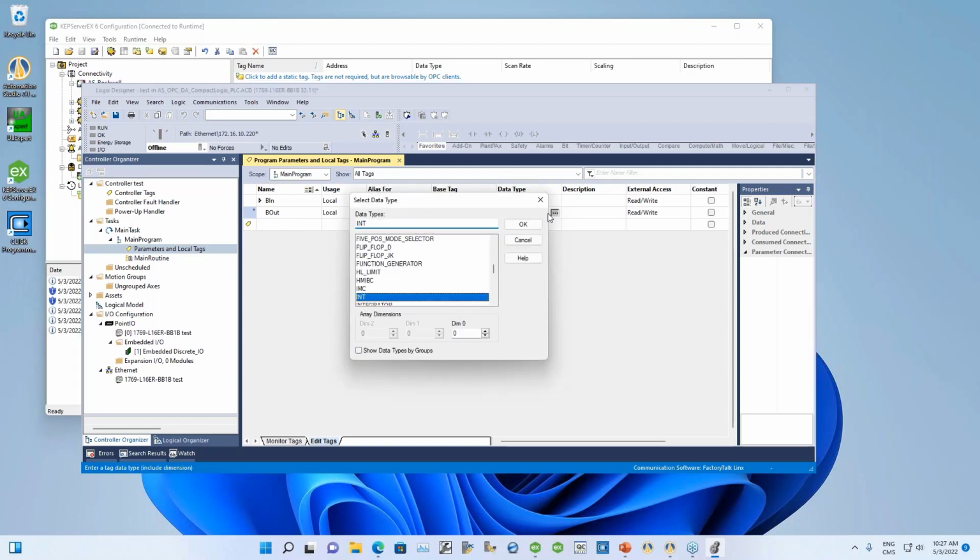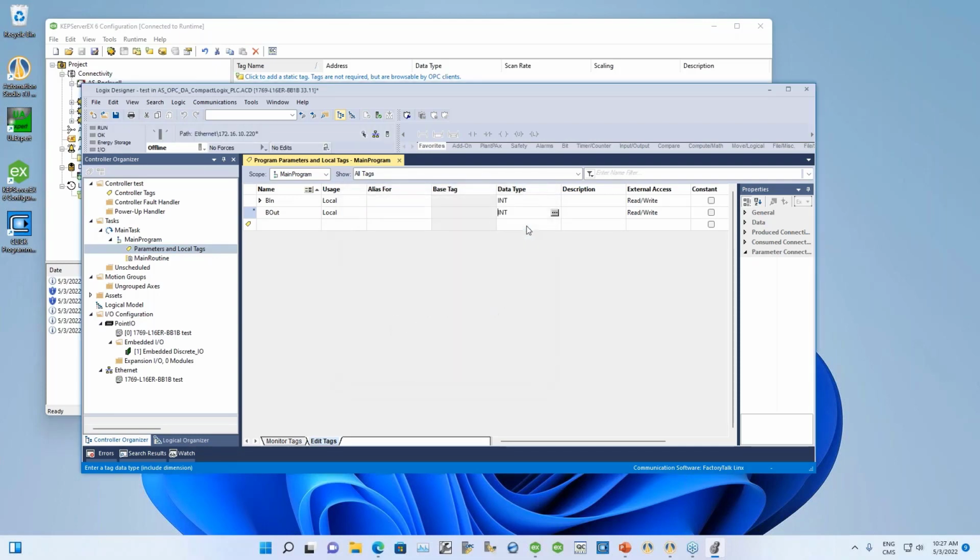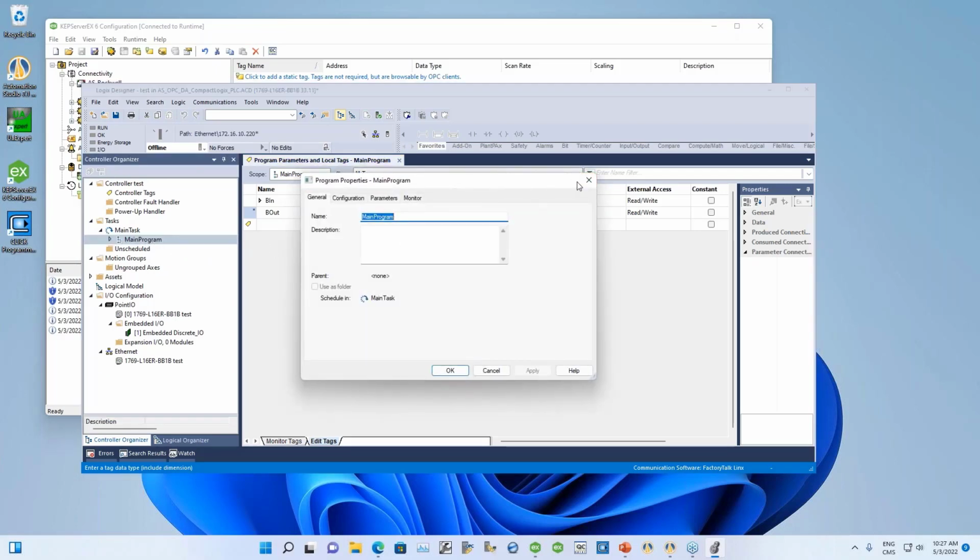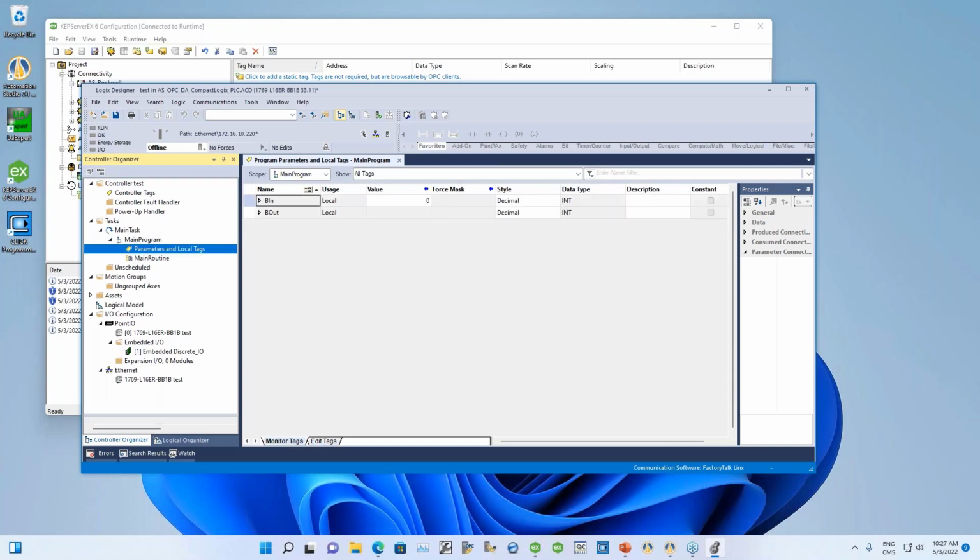And then it's int. For you guys who were doing PLC programming, you're going to come and ask, why are we doing that? We should be using registers, for example the ones in the PLC. If I go there, you're going to find that I have the local registers. For example, in the monitor, in the tags, you can see I can access the local register for input and output, which directly address the I/O cards. In order to do this communication with Automation Studio and simulation, we cannot use the direct input and output cards in the simulation.